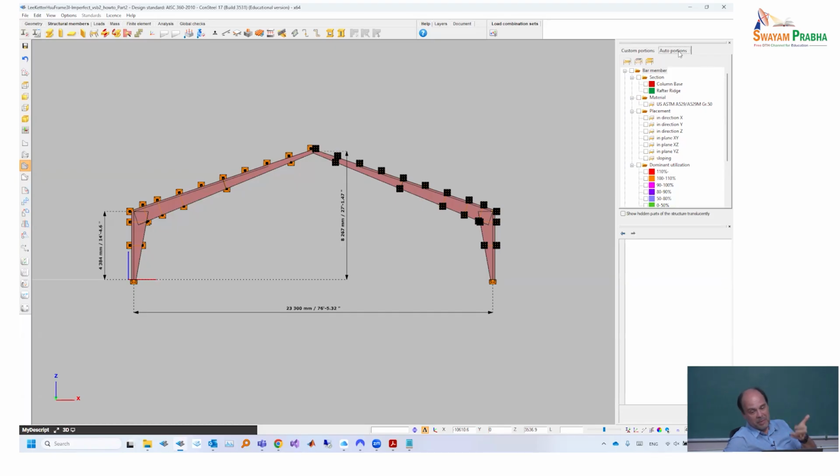Portions are maybe a bit strange name in Consteel for a group of elements. You can use a portion for many reasons. You can even assign elements to portions to say they are already checked by my friend, or I'm not sure if it's good enough, or to be replaced tomorrow, or to be shipped to the job site, already produced but not erected yet. You can do what you want.